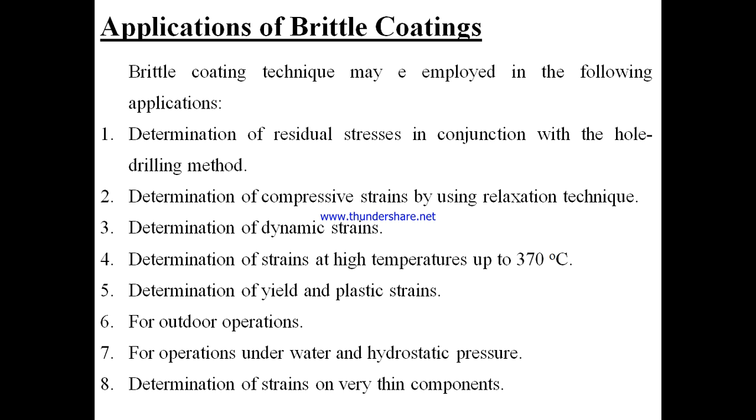Then yield and plastic strains can be determined. These brittle coatings are used for outdoor operations. They can also be used under water and in hydrostatic pressure operations. Then at last, for determination of strains on very thin components, these brittle coatings can also be used.